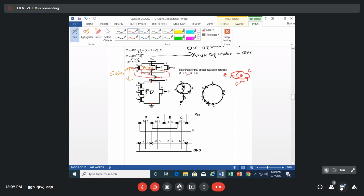Okay, so this is the pull-up network, and now the pull-down network. The pull-down network is very easy, because the connections here we can directly know how to draw. The source terminals of the MOS transistors are connected to the ground. Not all, but only two transistors here, the transistors with inputs C and D. So we can determine the connections here.